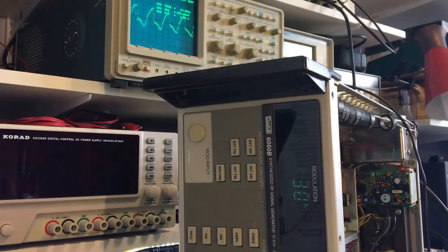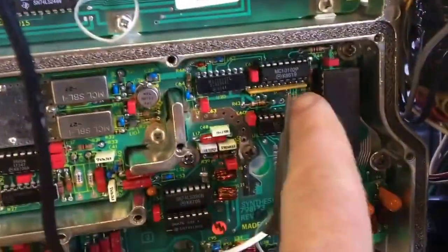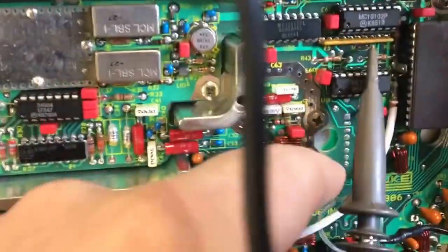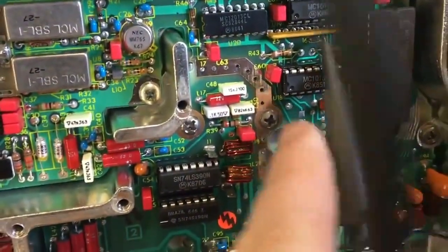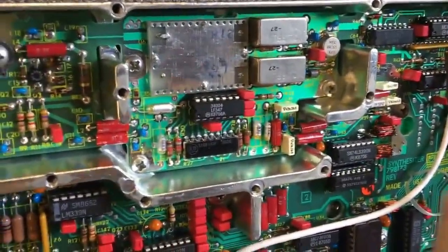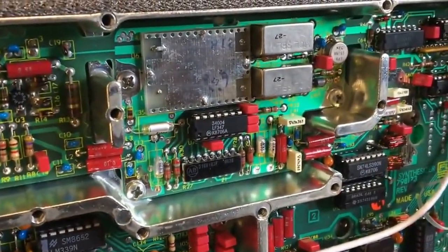working on it. I did a couple of videos troubleshooting, trying to find the 20 megahertz offset which I had. Trying to trace that down. And the closest I found was noise on this pin 16. It's test point 16 just here. I had lots of noise there, which is fed partially by this IC I just changed here, the MC10131. So it's fed from that, in that area. It's all linked together, part of the phase feed and everything.